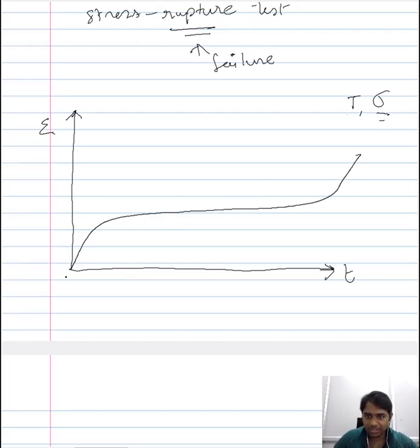You would have your instantaneous creep, transient creep, a large amount of steady state creep, and finally your tertiary creep. And like we discussed earlier, once the tertiary creep sets in, the overall creep testing process is stopped and the analysis is continued. Now this is a conventional outcome of creep testing. Now let us see how a similar curve would look for the stress rupture test.